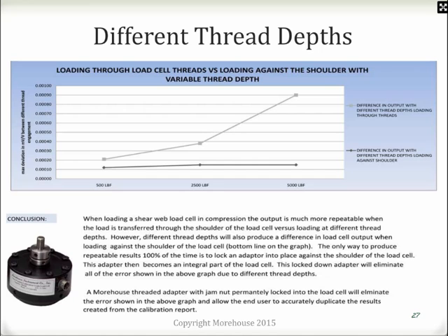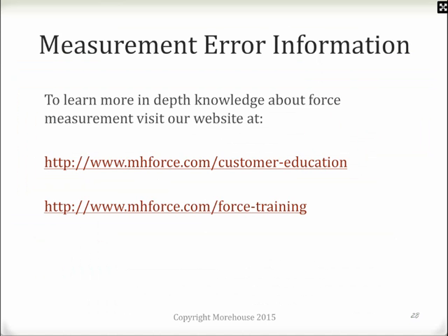When we do these, we typically preload a cell to 100, 120, 140%, and then we hand tight them in, or we use a spanner wrench. We lock them in. They're to remain locked in place. If a tech is out in the field and takes them out, they're voiding their calibration, or they're really increasing their measurement uncertainty by an amount of up to 0.05% or more.